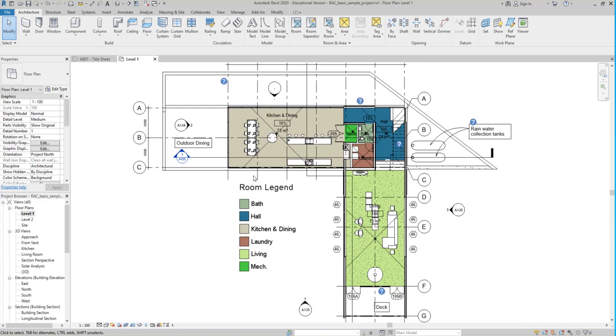But for any other type of construction drawing, we had somebody who's going into mining here. I was thinking it was you, right? Even included in that is you, right? So line weights are going to be associated with the graphic quality of a set of drawings, so you can read it, essentially, okay? I would assume that you're going to do a lot of topography in mining, right? So like major contours in a topographic surface, those will be like a very thick pen weight, right? And minor contours would be a very thin pen weight. So even that graphic idea translates to something like that, essentially.